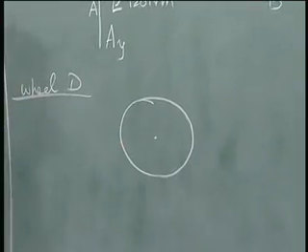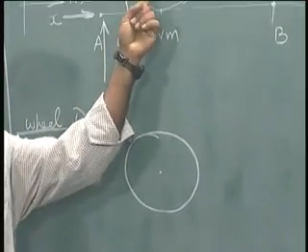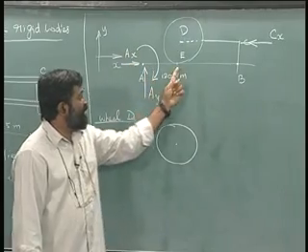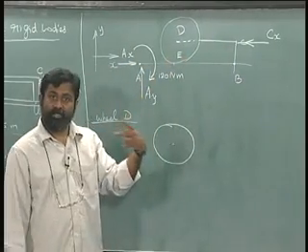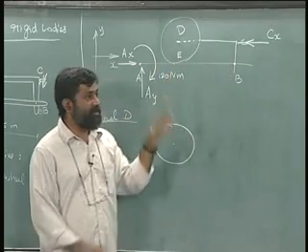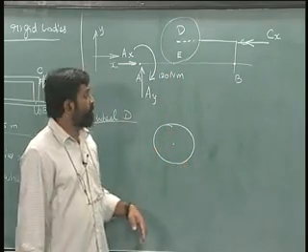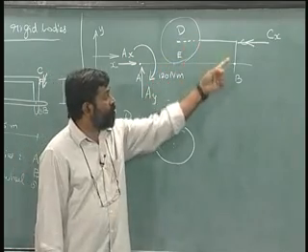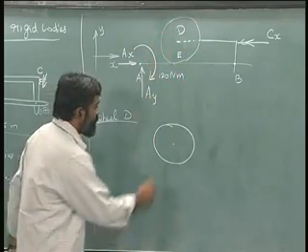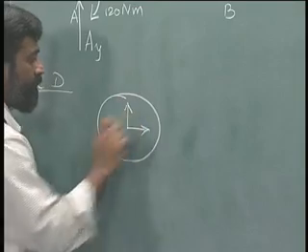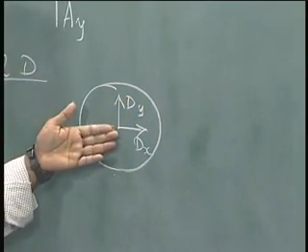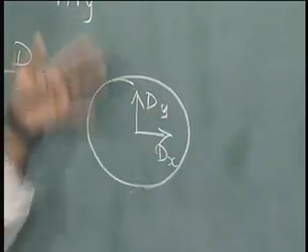What happens here, as we have discussed earlier, in order to draw the free body of this wheel, I need to make sure that I fix AEB and BCD, the two other rigid bodies, to the fixed frame of reference, which means AEB and BCD are not moving at all, in which case this point D of BCD will restrain this wheel from moving in x as well as y direction, which means I will have a reaction that appears on the wheel as Dy and Dx that is responsible for preventing motion in x and y.